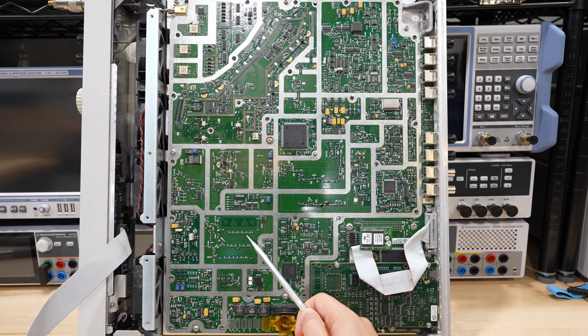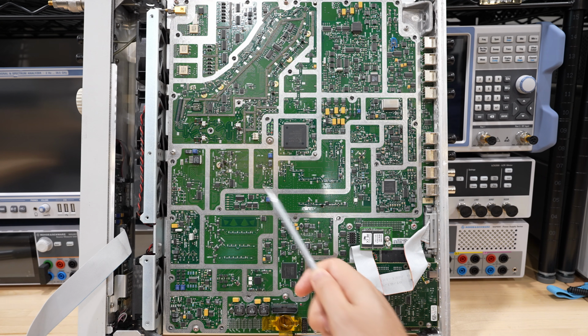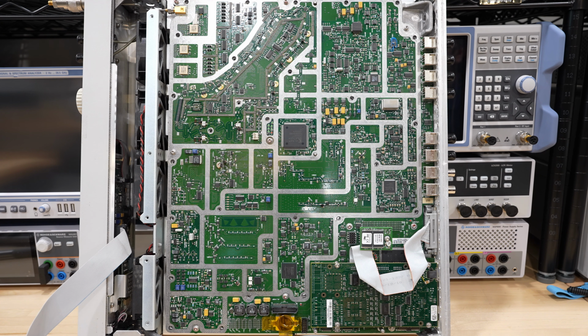These are using LC components, so probably the lower band frequencies. And there are a lot of other filters embedded inside of the PCB which we don't see. For example, these sections over here have tons of bandpass filters. We've actually done x-rays of these kind of boards before, and we know how they're making those. They're embedded in between the layers, and that allows them to, first of all, not radiate out, as well as really retain the space, because you can put additional things around it if you need to. So it kind of all makes sense.